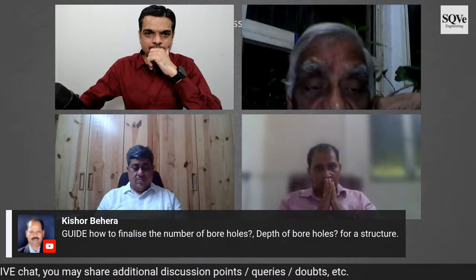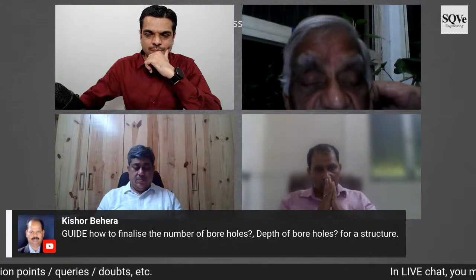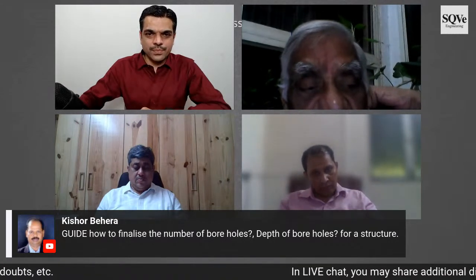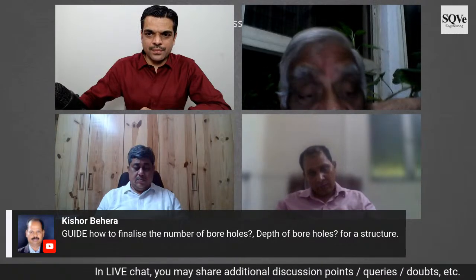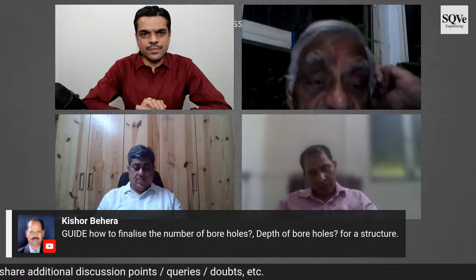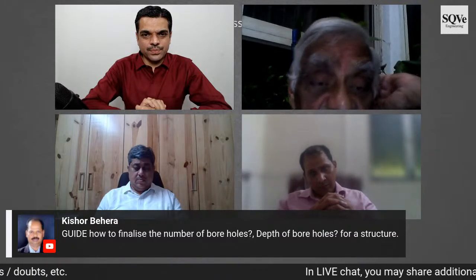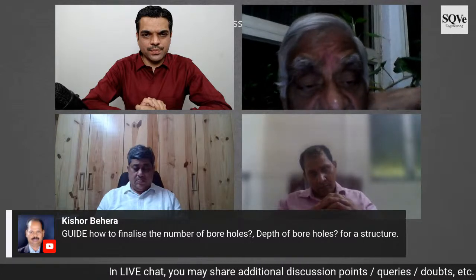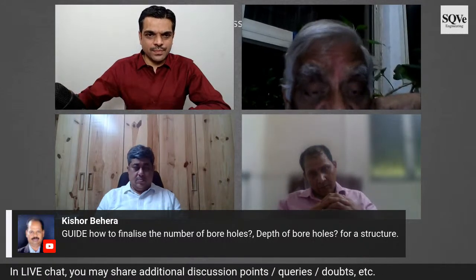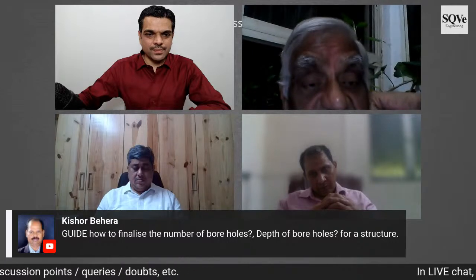Like when we talk about piles, and when we did the work in Johor Bahru Strait for Malaysia Electricity Board, that was around 75 or 76, the negative skin friction that would come in the soil, and what is the capacity of the pile. Or when we did it in Krishnarajpatnam port, where we were not really looking at the negative skin friction so much. But every time being conservative with this soil investigation expert, we had to literally fight.